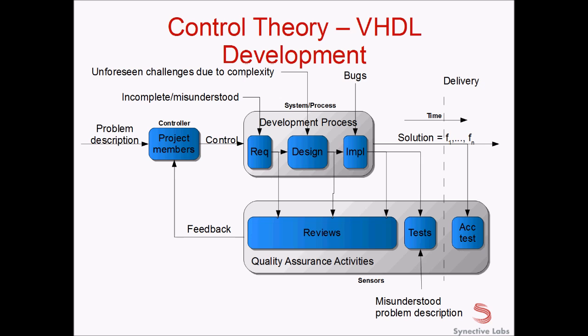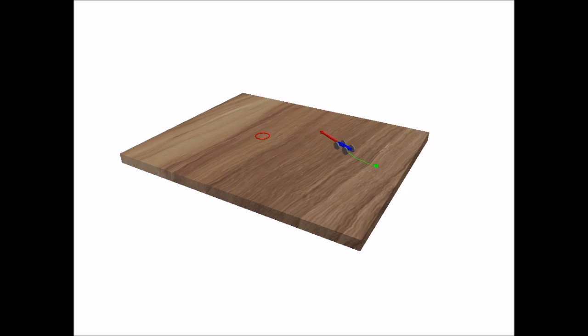If you remember the first car animation, I did take back-to-back samples on my feedback loop. Now, in reality, it might be that after I take a sample at the green dot, there is some processing delay before I can apply new control at the blue dot, and then I take a sample again. This means that I get a lower sampling frequency and a delayed response. And both these things are bad for the performance of the feedback loop, as you can see in this simulation.